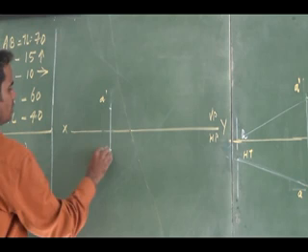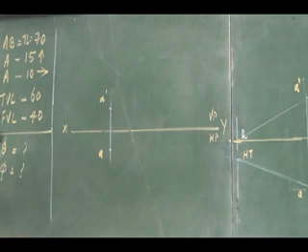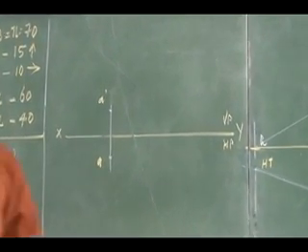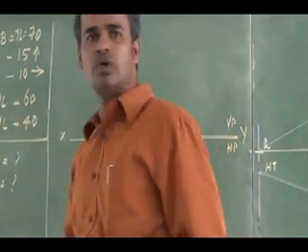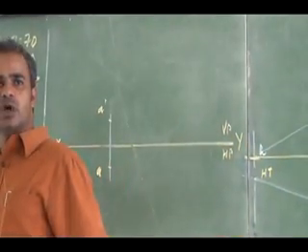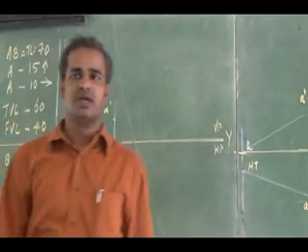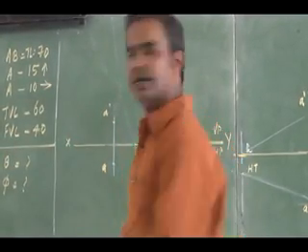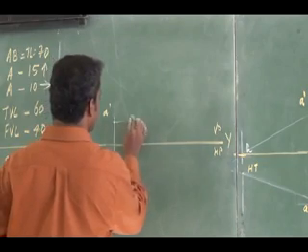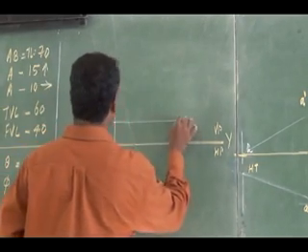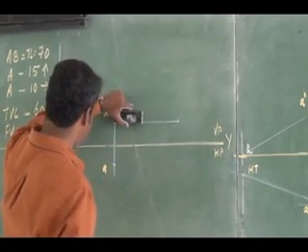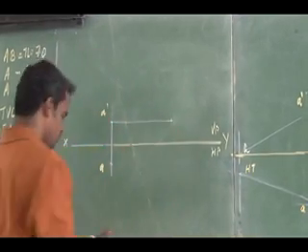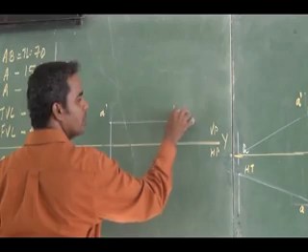A dash A. Then true length is given, top view length is given, front view length is given. Where will you use the front view length? Which is the front view length? A dash B2 dash. It is horizontally above the reference line. So I can draw a front view length of 40 mm. I can draw the front view. This is my notation B2 dash.